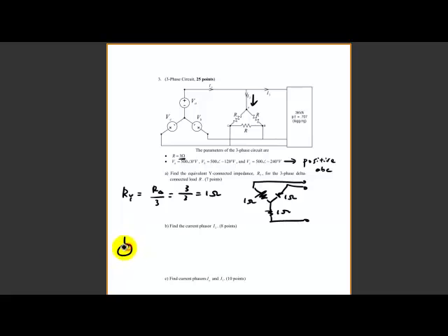So you have a voltage source, and in this case there is no sending resistor here, so we simply jump into the resistor here, which is 1 ohm. That's the part that we are talking about. Let's say we pick phase A, and in this case you have 500 volt, and this is actually line to neutral, because if I gave it to you as AB, that would be completely different. So this information will be just simply 500 volt.